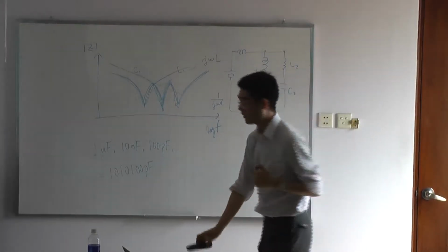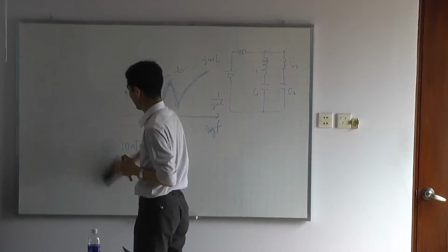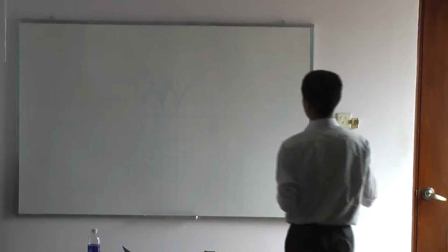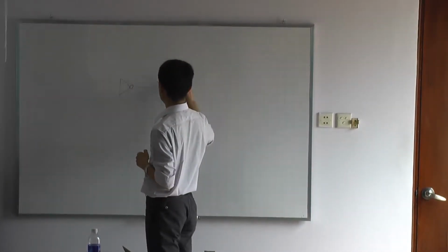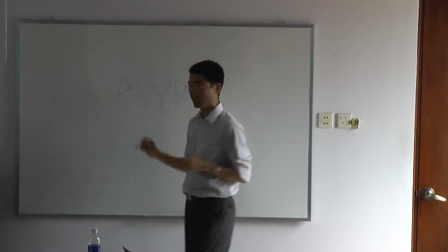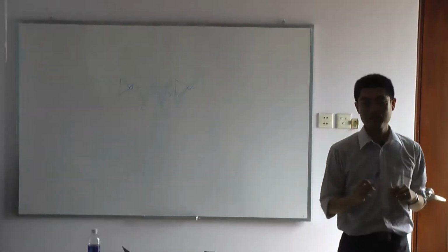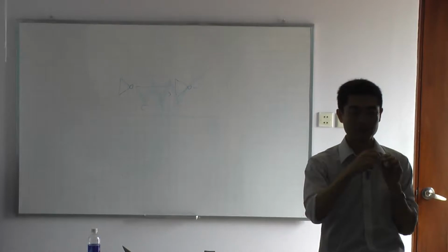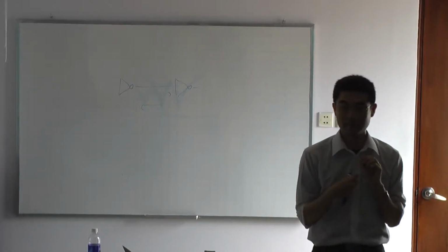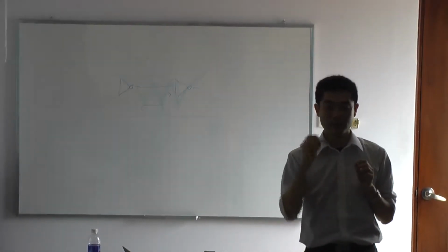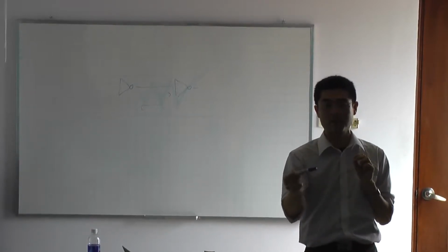And another topic is about the return path. Usually we draw the line, for example, for inverters, and we see that the current goes this way or this way. However, once the signal goes, another signal has to come back. So the current always loops. When the current goes, the same amount of current has to come back.